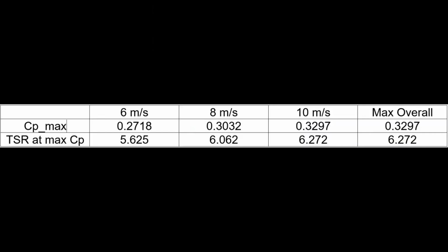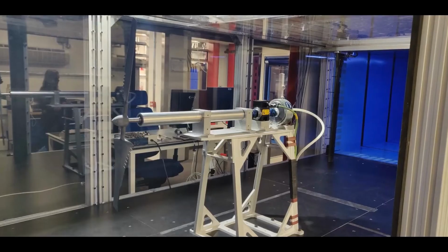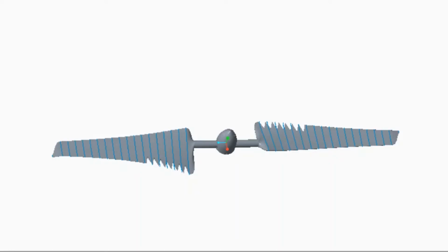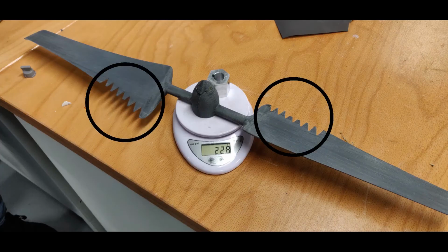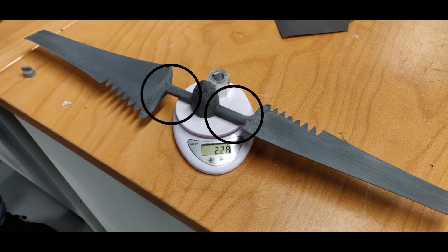Despite the failure, our turbine tests were very encouraging. It obtained an average max CP of 0.3 at an average TSR of 6.0. Blockage effects in the wind tunnel affected these results. It is difficult to evaluate the influence of our features on performance, as we had no control test. No way of knowing if it indeed controlled trailing edge flow or reduced noise. It certainly looked nice. Definitely reduced bending deflections.